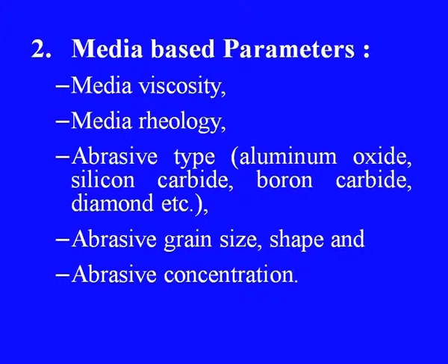Then very prime factors in media related parameters are media viscosity, media rheology, then abrasive type, for example, whether it is aluminum oxide, silicon carbide, boron carbide, diamond, etc. Then abrasive grain size and shape. Of course, not much investigation has been carried out regarding the effect of abrasive shapes on the quality of the machined surface.